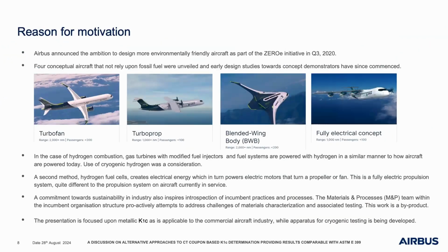Background: why am I doing this? Airbus announced ZEROe in 2020. We're looking at the use of hydrogen aircraft, both by direct combustion and by use of fuel cells. Direct combustion involves the use of cryogenic hydrogen, and regardless, materials will come across it. We will need novel testing methods. We are, along with industry, working on means of cryogenic testing and testing with hydrogen.